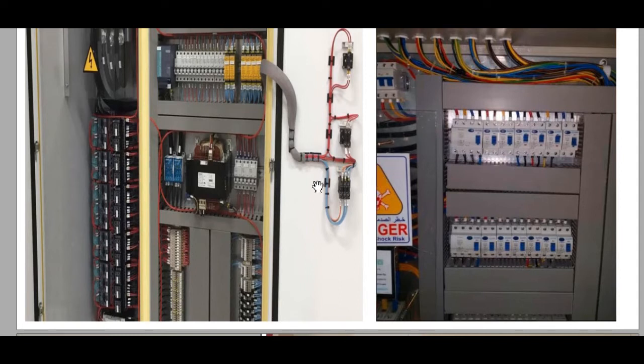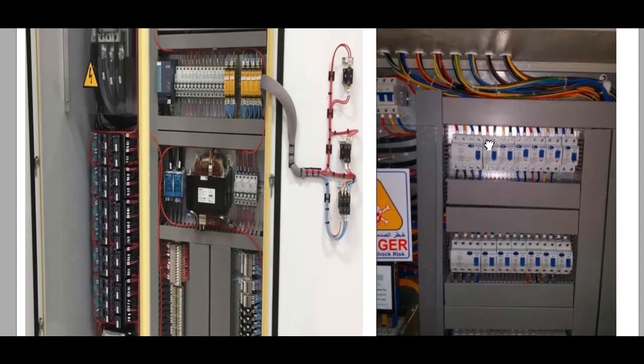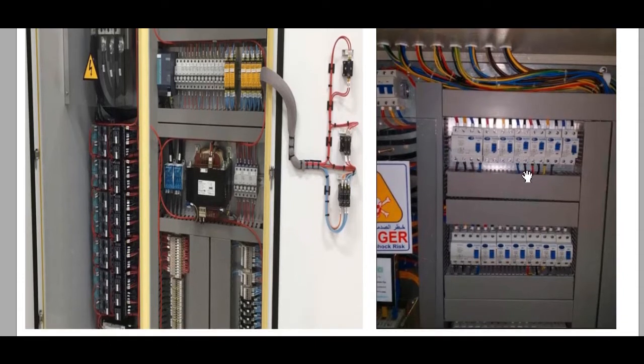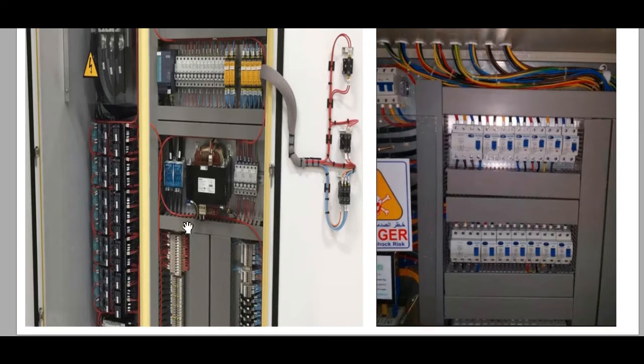We just focus, and we will see here, for example, this is good condition of these wires. Here all the wires have boot lugs, and also here is the numbering. This is a very nice view regarding the wires, but we have a big problem in this area. You see these wires, they are outside the installation rules. So these wires must go underneath the cable tray.